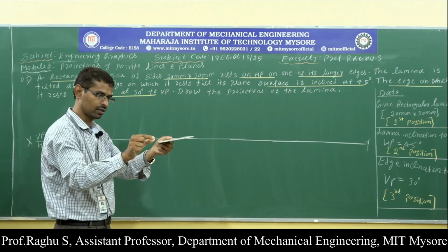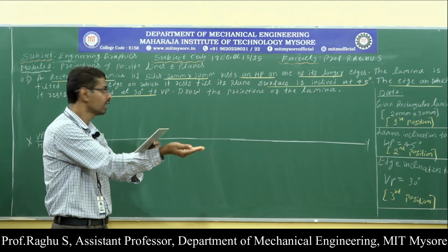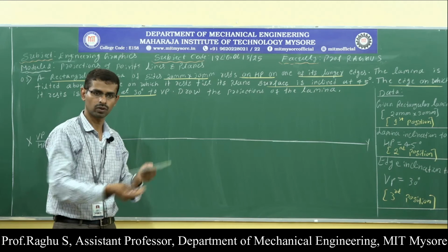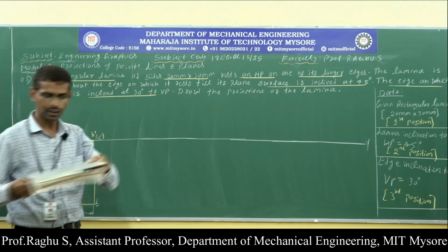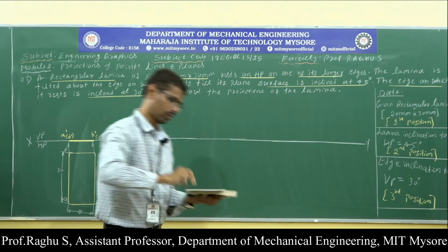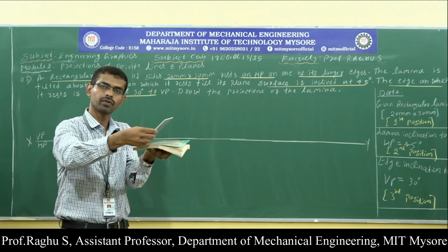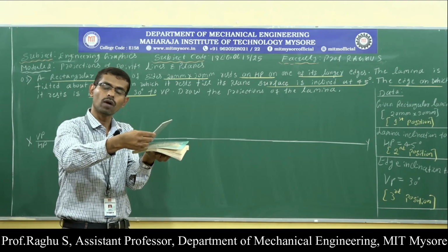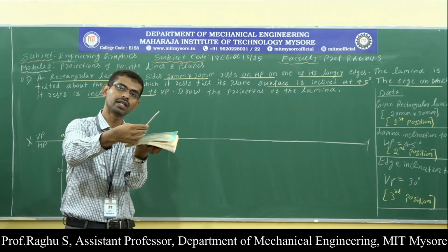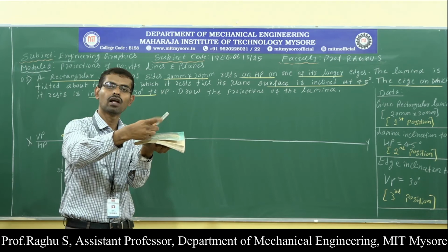This is the resting side. Now I am going to tilt the lamina about the resting side such that the plane surface makes an angle of 45 degree with respect to HP. When you tilt the lamina about the resting edge, in the front view I am going to see the inclination of 45 degree. Now you are the observer, so you are going to see the inclination along with this line.